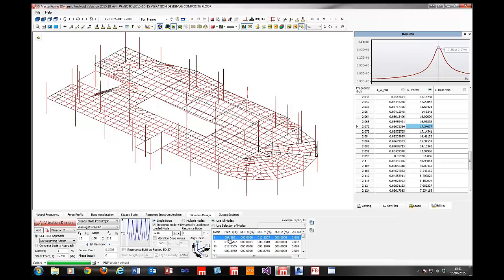But effectively, this is the mode shape, and that's interesting because 2.07 is a factor of 8.29, and in fact it is the fourth harmonic. So if we take the walking frequency of 2.07 times 4, we're almost bang on this natural frequency, which is why we're getting this resonance with that particular frequency there, because it does fall in the range of the harmonic of this mode shape here.